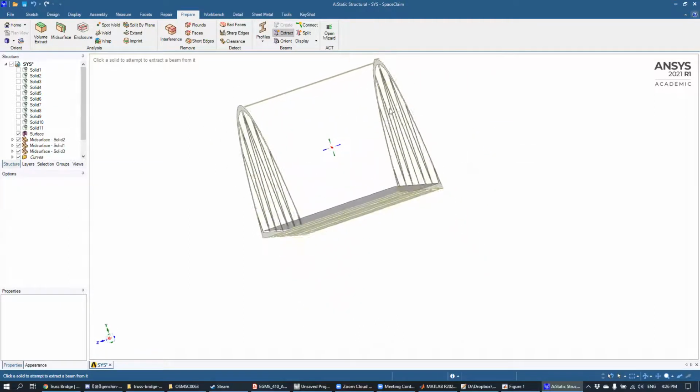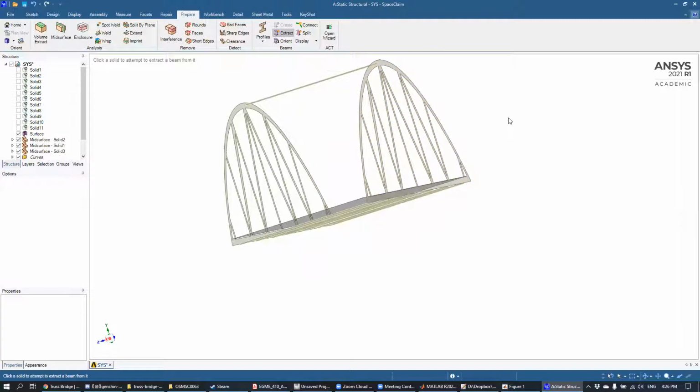Okay. All right, and so I'll say for this example, since everything here was thin or slender, we converted everything to beams or shells. But it could be that in your final project or any kind of model that you're doing, only a portion of your geometry can be replaced with shells or beams. Okay? And so that's okay. And so you can have parts of your model which are still three-dimensional and parts that you've converted to shells and beams. Okay? And so definitely mix and match and try to see what works the best for you.